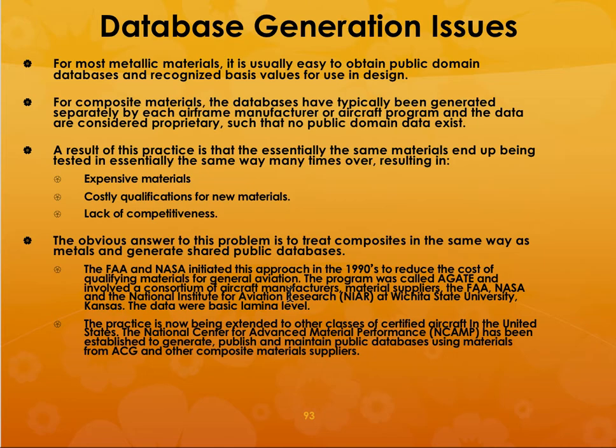The data is all based on basic laminate level, and this is being extended to other classes of materials. They call it the National Center for Advanced Material Performance, and it has been established to generate, publish, and maintain the public databases, especially for out-of-autoclave type of materials.